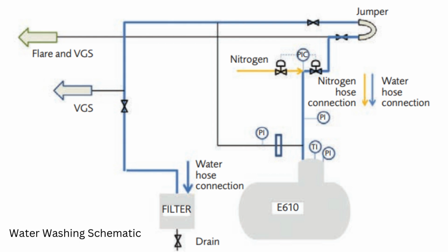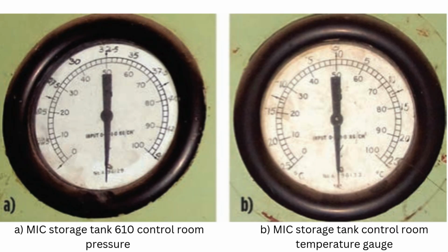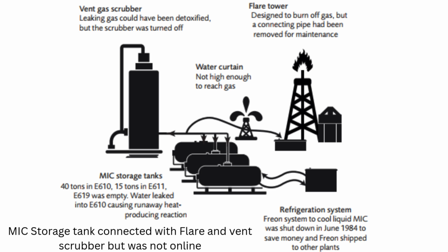At 11 p.m., workers at the Union Carbide plant in Bhopal observed a rise in pressure from 2 psi to 10 psi in tank 610, which stored 42 metric tons of MIC. This five-fold increase in pressure was dismissed as a faulty gauge because corrosion and poor maintenance made instrument readings unreliable. At 11:30 p.m., workers detected the initial signs of a gas leak, including a yellowish gas cloud and strong chemical odors. The leak was traced to tank 610 but was underestimated in severity.